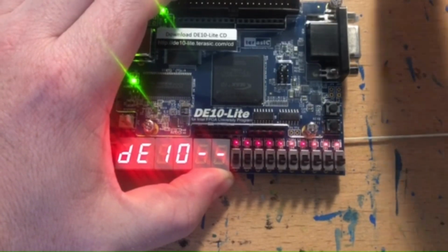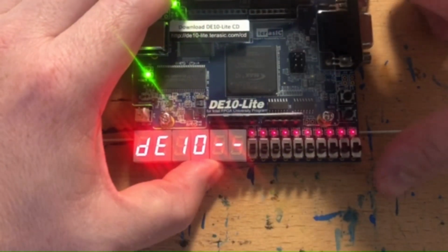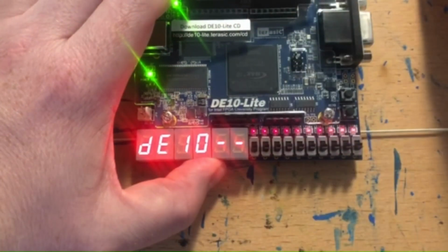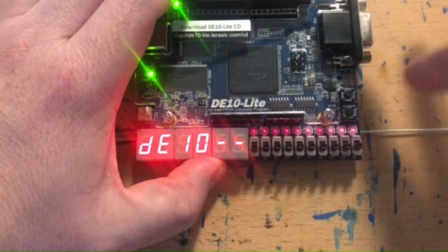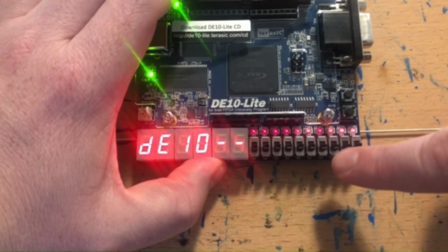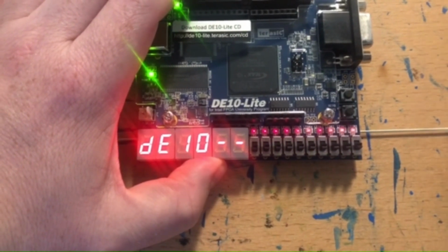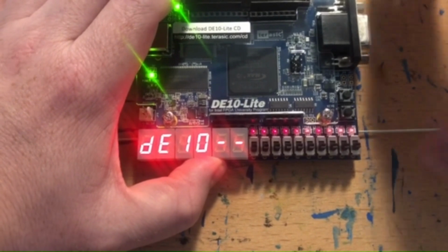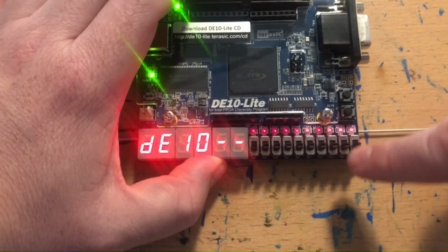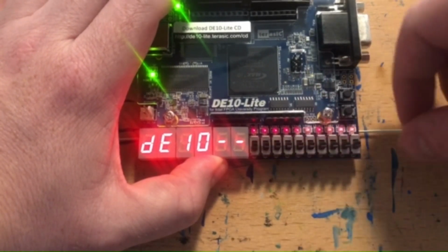Alright, and here is Lab 1 Part 6. We can see our DE10 and the 2 dashes on all 6 7-segment displays. I put 2 dashes rather than leaving them blank, just so it's easier to see that the word is rotating. We have our selector switches, and these other switches don't do anything, as we saw in the code. There are constants. And so what we can do to move them is just increment these, essentially treating this as a 3-bit binary number, and we can watch this move from left to right.